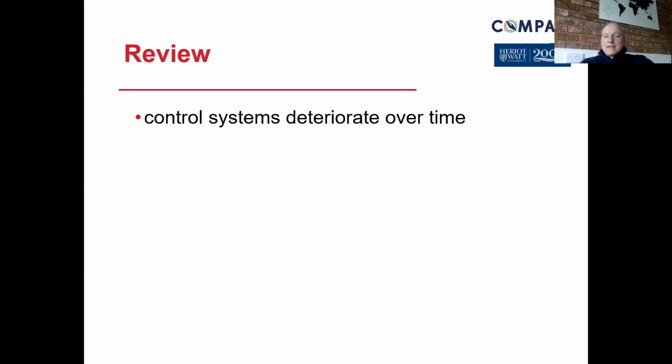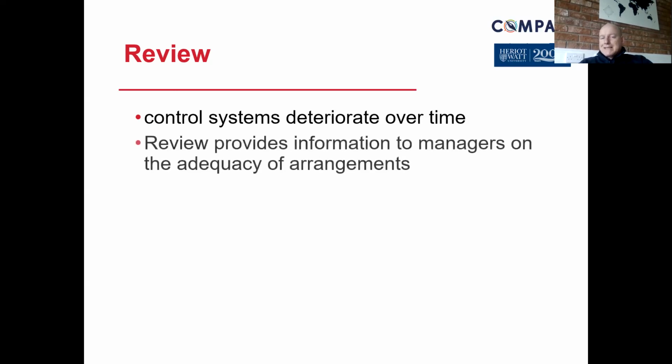Let's say Buncefield is an example where they had a switch there that's supposed to tell them that it's getting close to full, and it's supposed to make a safety stop so it can't be overflowed, but something went wrong. Why did it go wrong? So can it deteriorate? Yes, they can. What's the shelf life of it? How effective will it be? What maintenance is needed to bring it back to an acceptable standard?